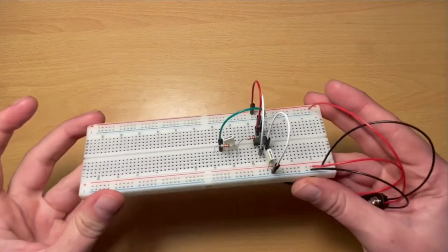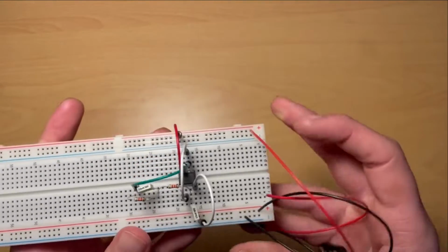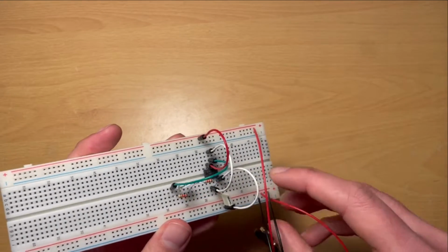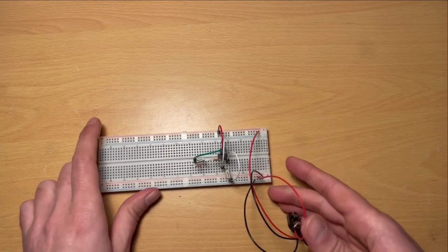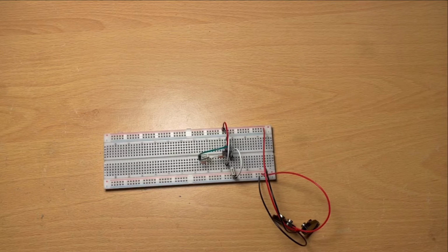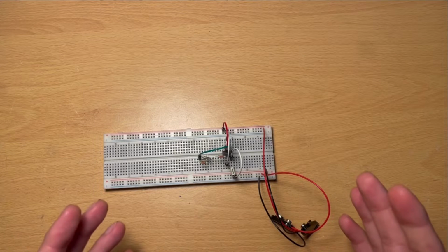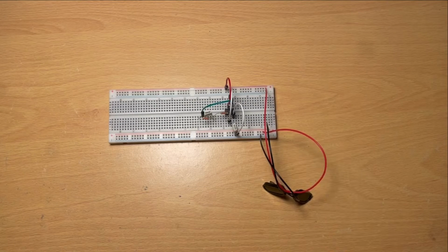In a previous video, we built this second order active low pass filter, and I've also just knocked something out of it there. But we built this circuit, and in this video, we are going to connect it up to, in our case, a USB oscilloscope, and we're going to take some measurements. And we're going to take measurements at different frequencies. And based on those measurements, we're going to start to assemble something called a Bode plot, which we'll do manually. And we're going to explain the different steps of how to do that.